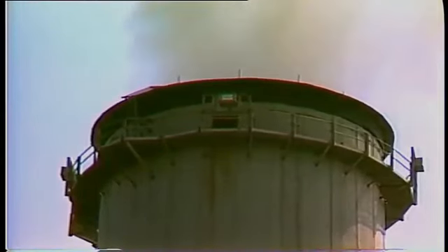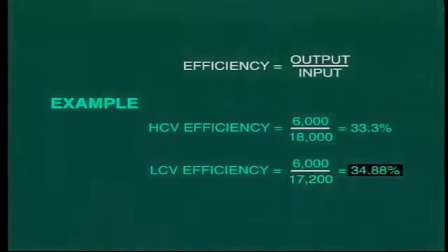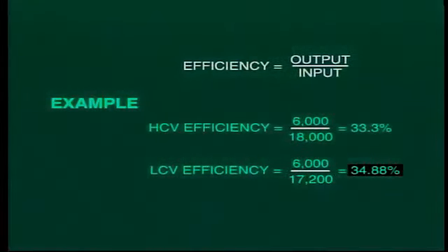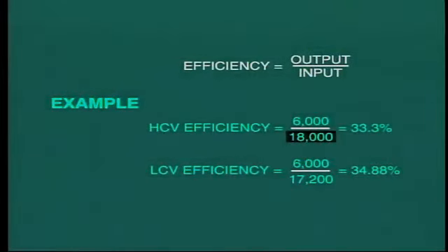However, beware, in many other situations, for example, in many European plants and European manufactured equipment, the quoted efficiency is based on the lower calorific value. This would, of course, provide an apparent higher number for efficiency. Clearly, if the heat input to the plant is indicated at a higher value, then the calculated efficiency would come